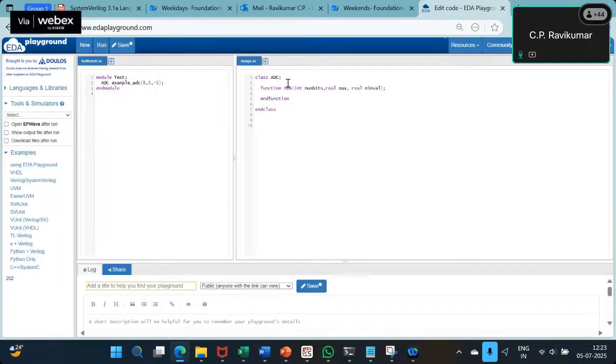So, see, some people have tried to improve these things. You don't have to go one step at a time. You can try to jump and come back. So there are some variations. You don't have to go linear search. You can do maybe binary search. So many such variations are there. But we are going to keep it simple. We are going to assume that it's going to just increment or decrement. The guess is always zero. We assume that the input voltage is zero.